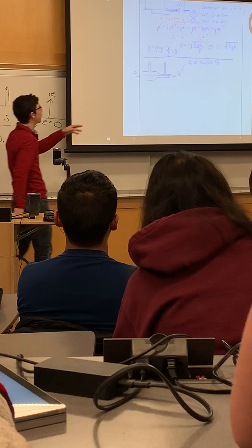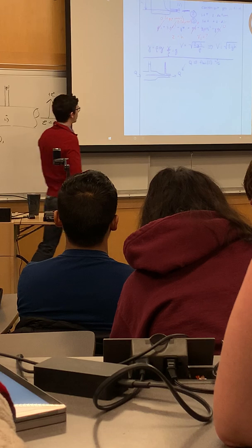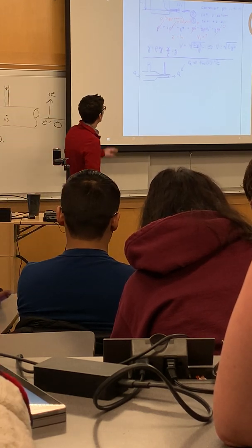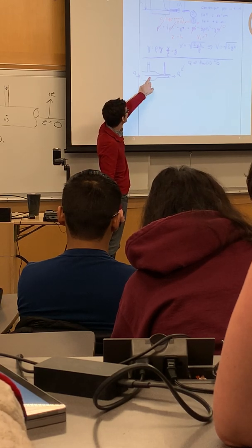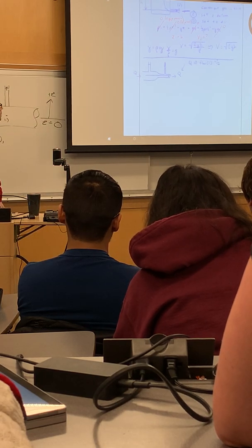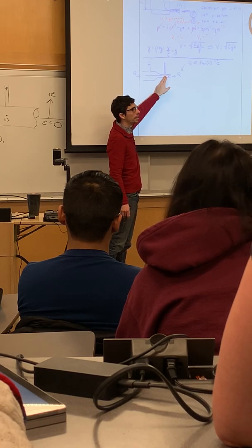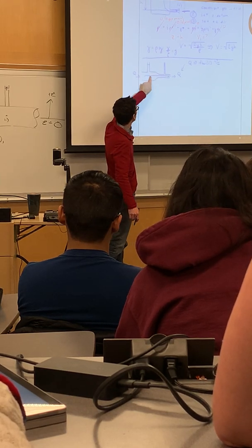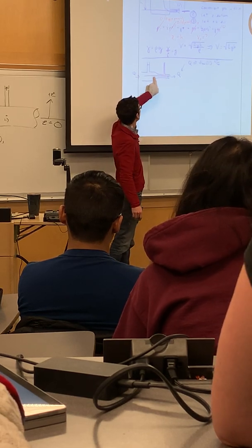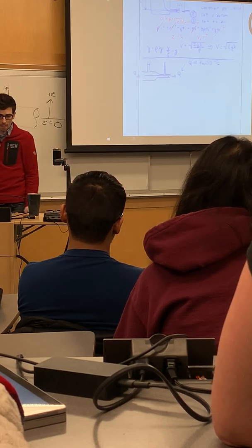There's fluid flow that moves from this portion of the flowing tube to this portion of the flowing tube. And hopefully you can be convinced of that. We want to drop the streamline at the center line because it makes our assessment of the static pressure a little bit simpler, right? Because then we can describe a datum relative to a constant center line and describe the pressure at these 2 points as the height of these manometers, these piezometers.